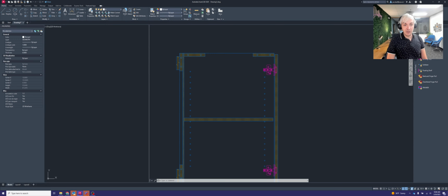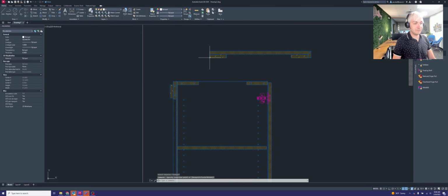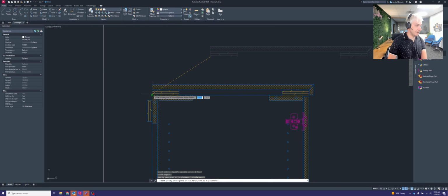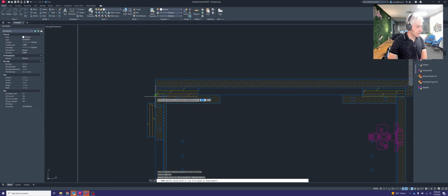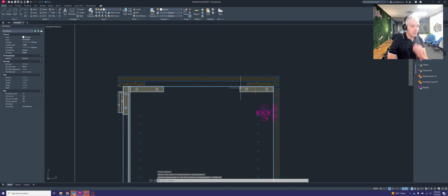All right, then you have your countertop block. This is a pretty new one. We're going to add that in here to our drawing. Let's set that down right there. And I'm going to use the move command again, and I'm going to move this to line up with our cabinet here. Oops, hold on a sec, sorry. I want to make sure that we're lined up like so.